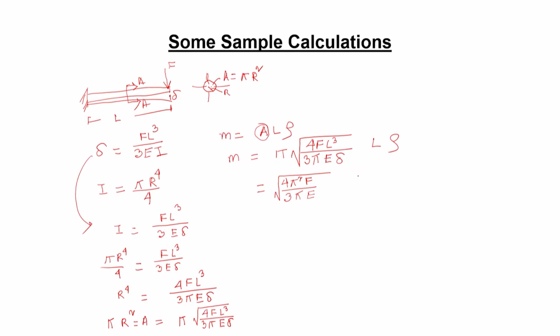So, which means you can have that geometry part here as square root of L cube and L together. So, it will be L to the power 5, and then we have the material part which we are looking for, and you can write it as something like rho square over E.